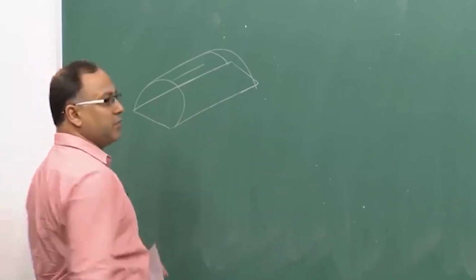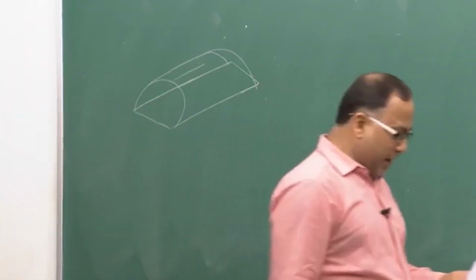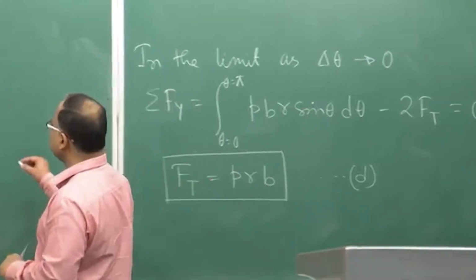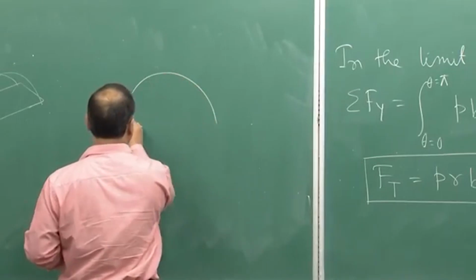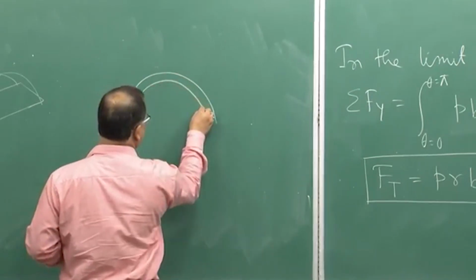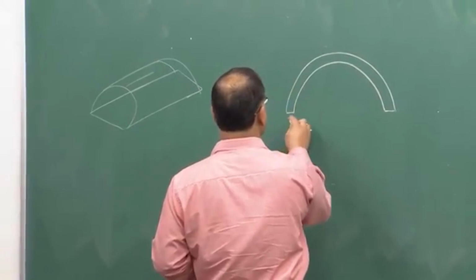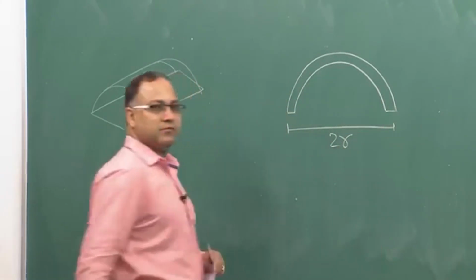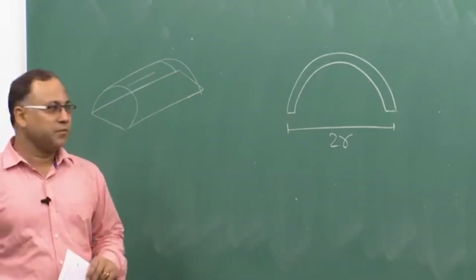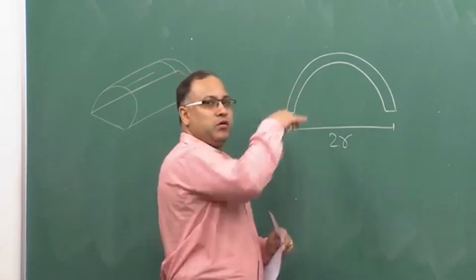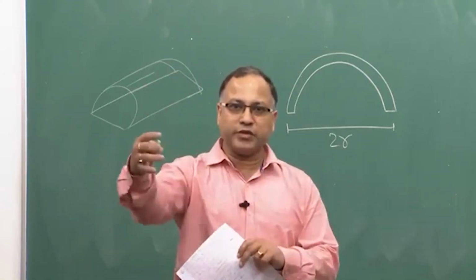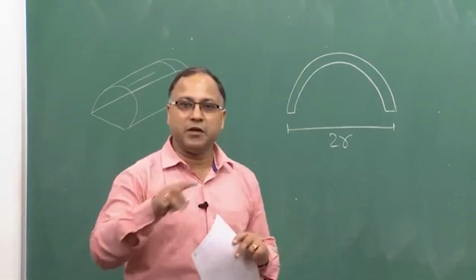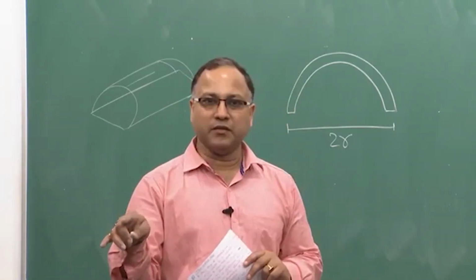So this is the plane. So this plane on that projected area, basically what I mean, even if you see this is your say upper half, okay. So this is nothing but your twice r, that is the diameter, and normal to the board is your b, that is the width. So the projected area of this hoop is nothing but twice r into b, right.